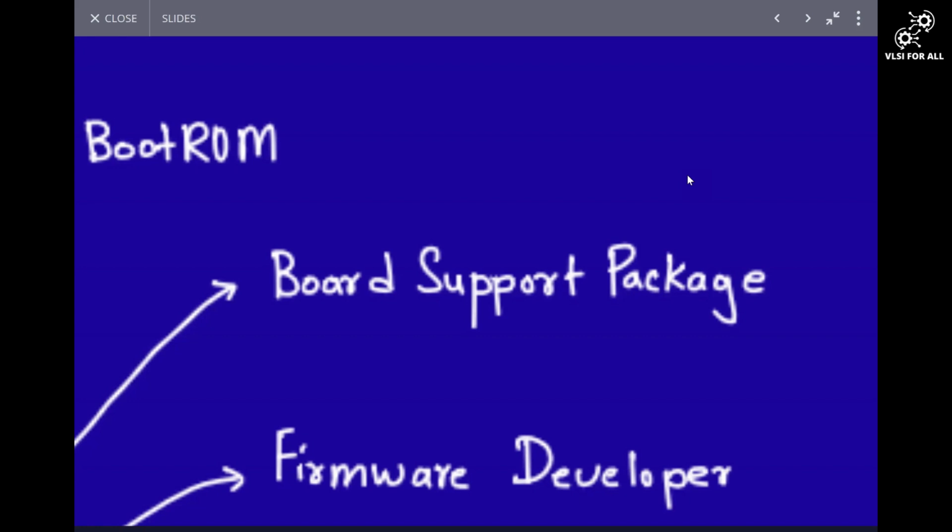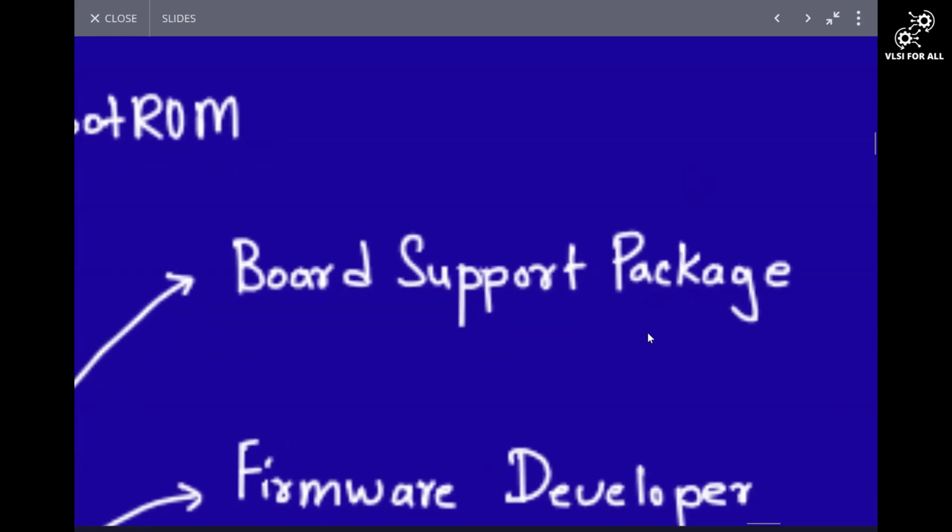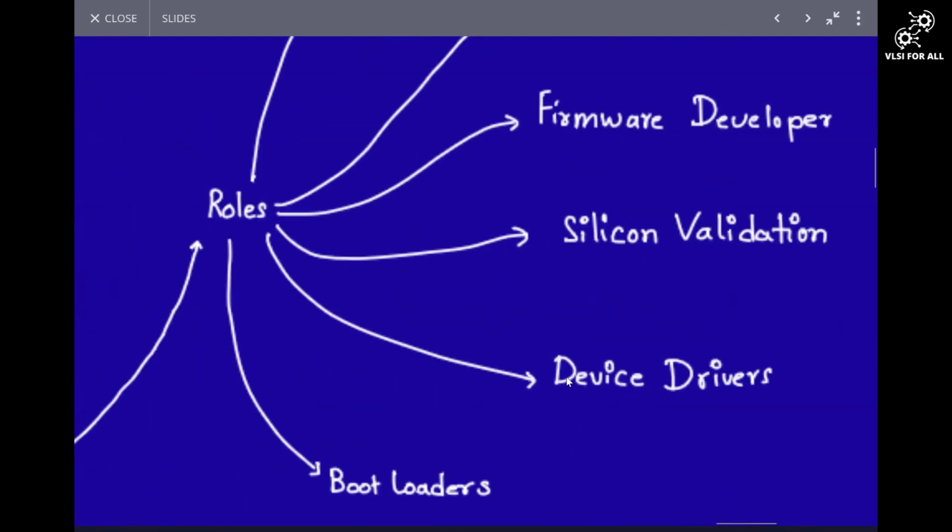So all these macros related to your processor and APIs related to your processor, you're putting them in separate header files such that any programmer, if they want to work with that processor, they import these header files into their program and use them, right? So that's the basic concept of a board support package, right? There are other aspects as well.